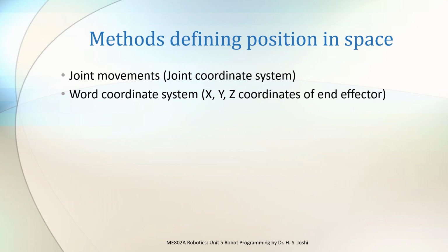In some applications it may not really matter, and reaching the required position is good enough, especially if you are handling a robot in an open space for a pick and place operation. If there are no other restrictions on the robot, then the XYZ coordinates of that point may be enough. But in many applications there are some restrictions, so we need to define that separately during programming.